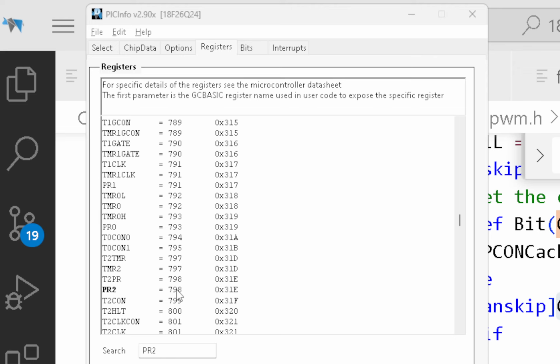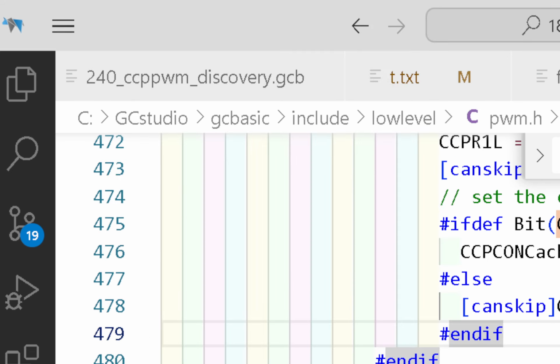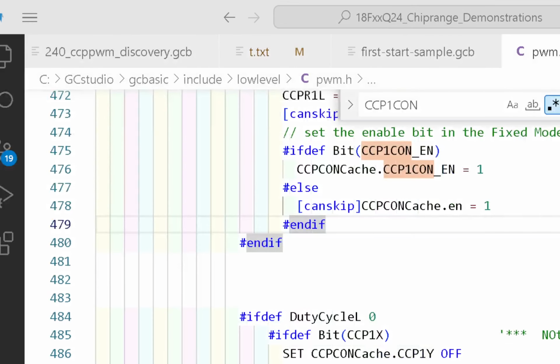Well, guess what? Inside of PIC-AS, they've dropped PR2 for this particular chip. It's gone. It's disappeared, I don't know where, but it doesn't support it. So you now have to use T2PR. And so the scripts in the libraries have to take care of all this, otherwise it will fail. But back to our problem here, which was getting this one going.